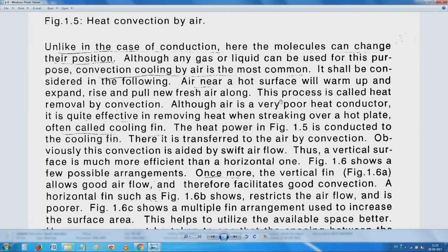Air is a very poor heat conductor, and then all your insulation depends on trapping air in closed cells. So, typically if you take expanded polystyrene or polystyrene foam or PU foam, you have cells inside. If it is closed, it is very good because it will prevent ingress or condensation of moisture, and air is the one that creates the insulation. By themselves, there are no insulating materials as such. All insulating materials depend on air as the insulator. Same thing with your jacket.